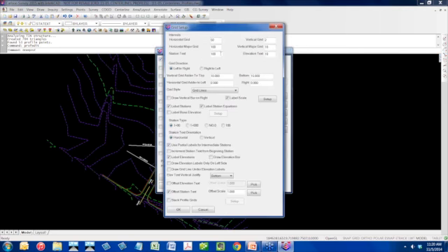So for my horizontal grid, I'm going to have a vertical line every 50 feet and a major grid line vertical at 100 feet. And I'm going to label the stationing every 100 feet along the bottom. Along the left-hand side, I'm going to have a vertical grid every 2 feet, majors at 10 feet with the elevation label at 10 feet.